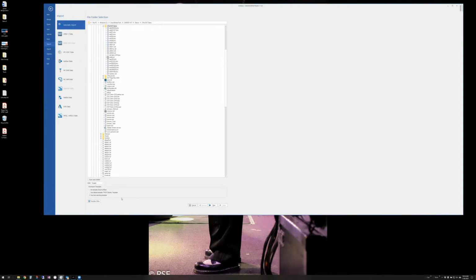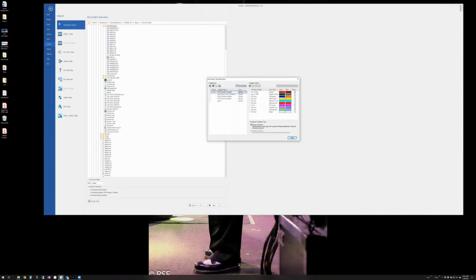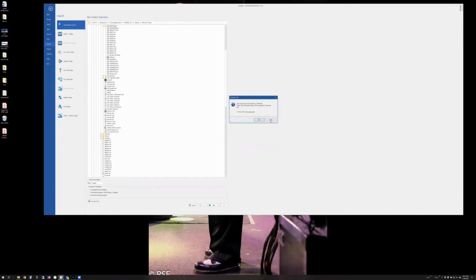Now, one thing you can do is use the template editor to look at file names. Often this is kind of overkill for fab because you're getting data from all different sources, and the file names could be different from each company that you're getting the data from. But I've also seen fab shops that have 100 different templates here, and it will go and look for the one that best matches the pattern that it sees. What it's doing is it's actually setting the layer types as the key. It also can set the colors for you.